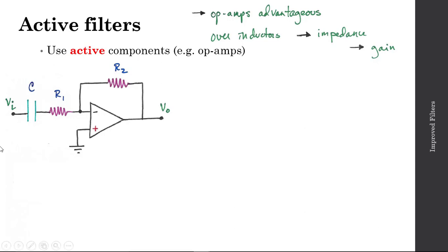Since this filter has an operational amplifier, we should point out a potential disadvantage of this type of filter, this active filter. There should be power rails drawn here, right? So I need a power supply to actually utilize this filter. And some could argue that would be a disadvantageous quality of these filters. Let's begin our analysis of this circuit by creating an equivalent resistance.